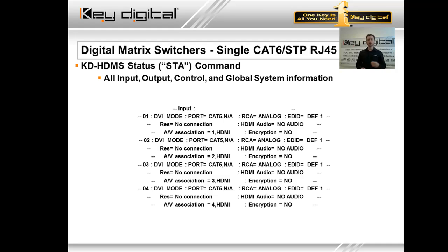You have input status. Again, this was pulled through terminal through one of our 4x4 systems. So you have 4x4 inputs. It tells you the port. Is it CAT or is it HDMI? As you can see right now on this specific unit, card 1 is looking for the signal on the RJ45 port, not the HDMI port. Of course, out of the box, it's always the HDMI, okay?